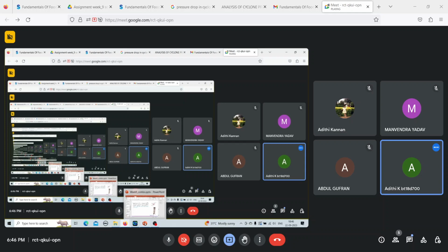So in the previous slide we calculated the pressure at the wall, given as rho omega square by 2 into R square minus Ri square. Omega is not in RPM. Omega is given as 2 pi into n, as we discussed in one of the previous questions. Omega can be given as 2 pi into n, where n is the speed of the centrifuge that is rotating in RPS.